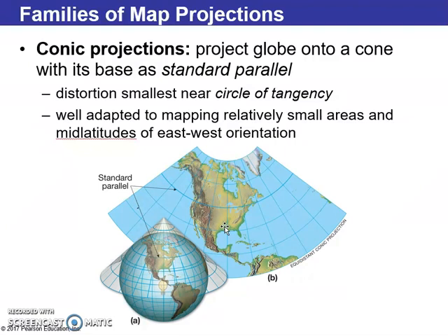Conic projections, these are used in very local systems, so if you go and buy a house or a property interest, or you look at a land title survey, they'll frequently try to keep those very accurate because of the legal implications, and they will be surveyed in a local conic coordinate system, which in the United States, that's all organized by state plane. Most state plane coordinate zones are conic. Some are UTM.